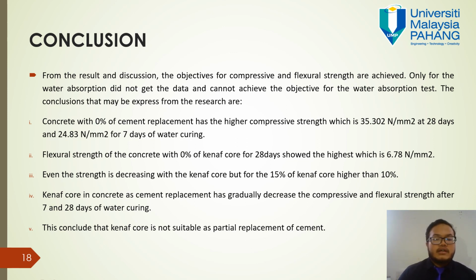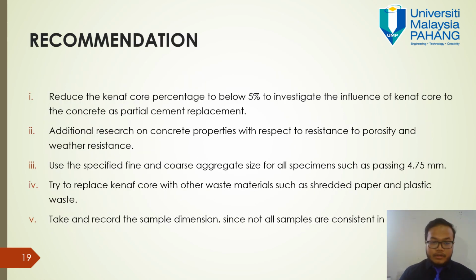Kenaf core in concrete as cement replacement has gradually decreased the compressive and flexural strength after 7 and 28 days of water curing. This concludes that Kenaf core is not suitable as partial cement replacement. So for the recommendations, firstly, reduce the Kenaf core percentage to below 5% to investigate the influence of Kenaf core in concrete as partial cement replacement.